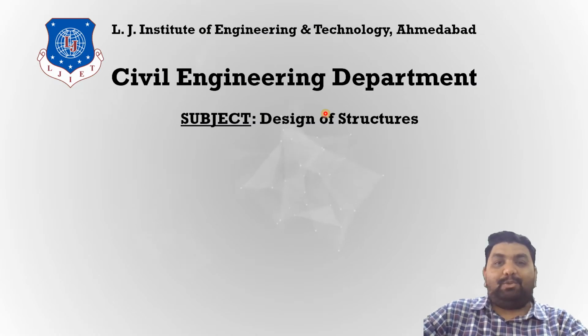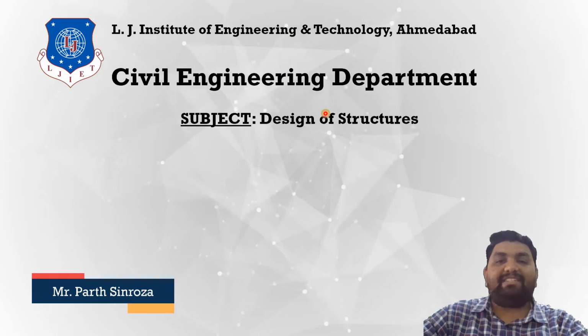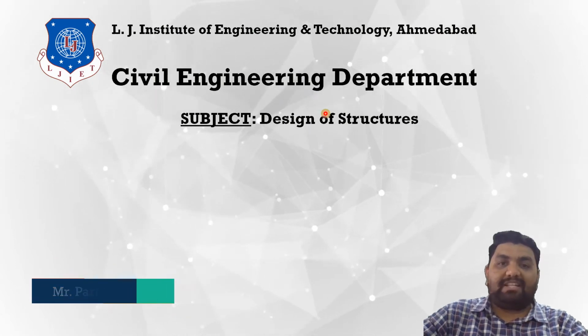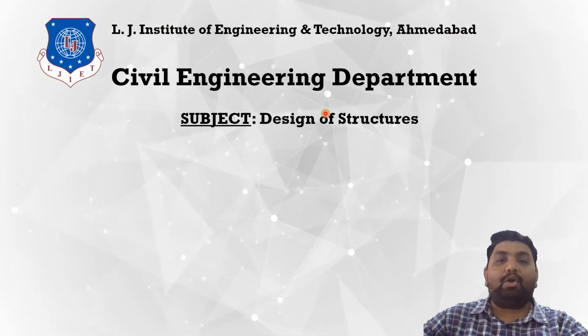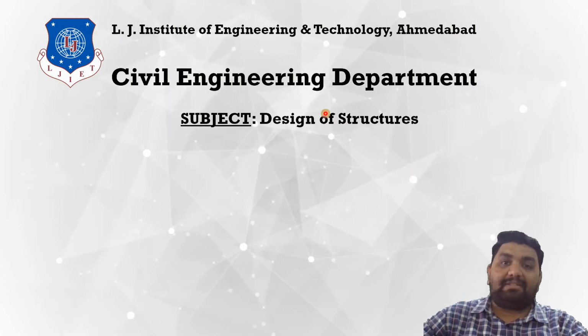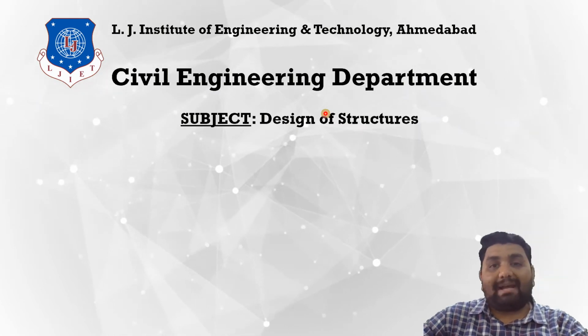Hello. So in the last session we discussed the analysis of T-beams, or you can say flange beams, and in that session we covered three cases in which the analysis of a flange section is to be done. The first case that we discussed was the neutral axis in the flange, that is XU is less than DF. The second case was that the neutral axis was at the limiting section.